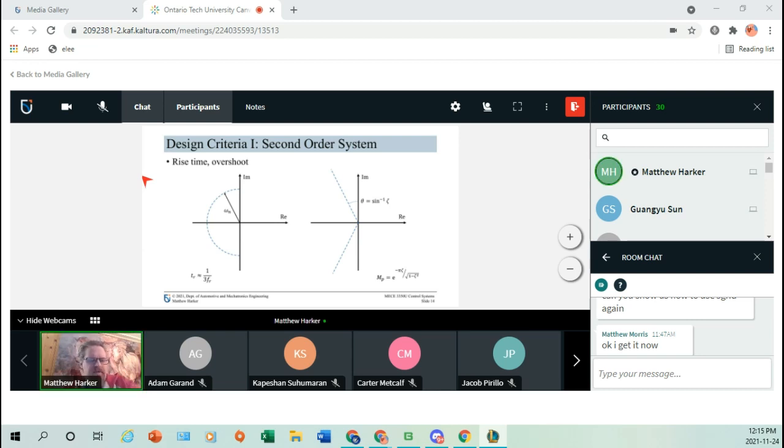Are there any questions about that root locus? Okay, so I think that should be lots of root loci to think about. Just saying that now if we have a controller with 2 parameters, we have more flexibility in what we can do, which means, depending on the range of the parameters that make sense, we can essentially set 2 design criteria, right?